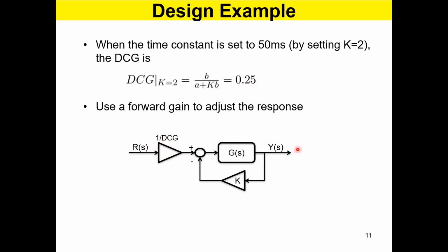So this whole thing over here, 25%, or 1/4. And here you invert it, 4 times. You put a gain of 4 here, 4x. Then what comes over here will be the same as R(s). That's very simple. So sometimes you have to draw, sometimes you have to sketch.